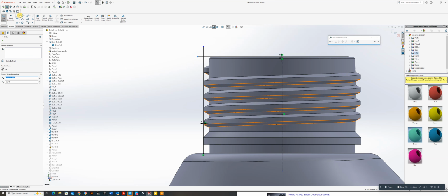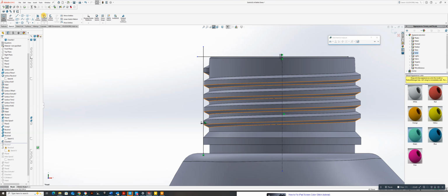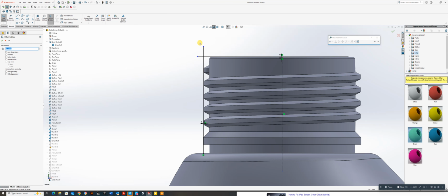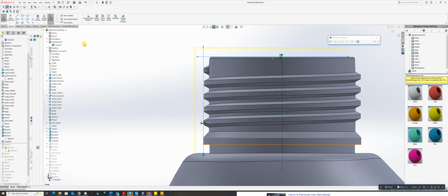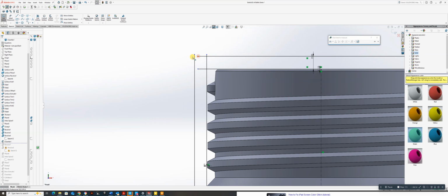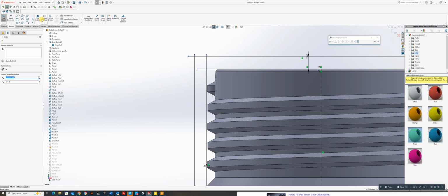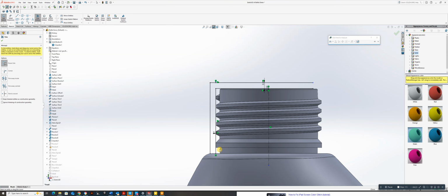I'm going to draw now. Probably something I could offset. Actually, no. Let's go to offset tool again. Not convert entities. What am I doing? Offset entities by 2 millimeters. That's still there. Let's do that. Yeah, 2. Do this one here as well. Out there. That'll be it for now. Let's just pull that along to there. Let's just trim this while we're here. I'm going to put a chamfer in on that for the bottle in a bit.